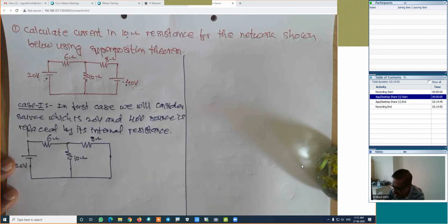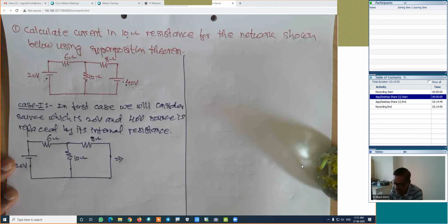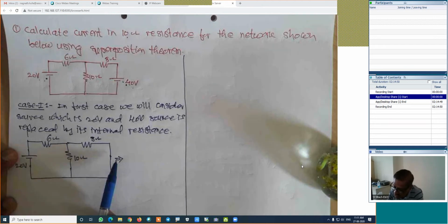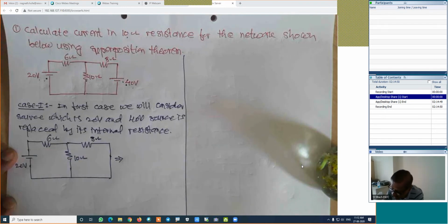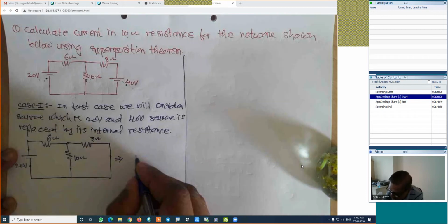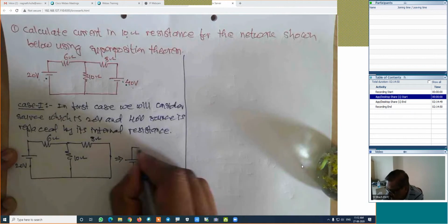Now, how is the reduction technique? I will reduce this figure. First, try to find out the total current. Then we will try to find out the current in the required branch. Since the source is at this point, we will reduce this figure from this end, and we are interested in the calculation of the total current. Here, these two branches are in parallel combination.